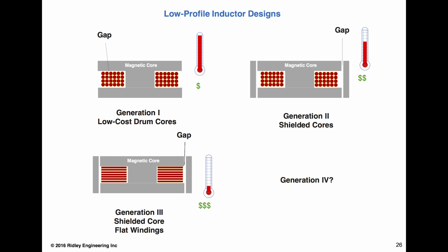They're using GaN sometimes because they like the low capacitance drive, but they're all zero voltage switching, and they're switching down at 50 kilohertz or 100 kilohertz. So incredible performance is achieved through different means. And GaN, we're still waiting to see. Yes, it's adding that last little 1%, but it's not changing the industry by a factor of 10 at this point that I see.